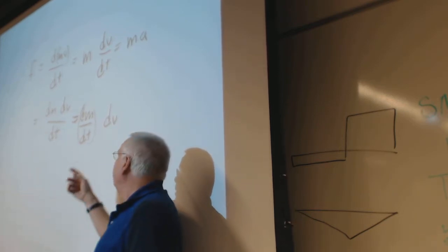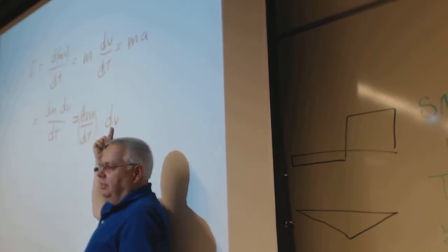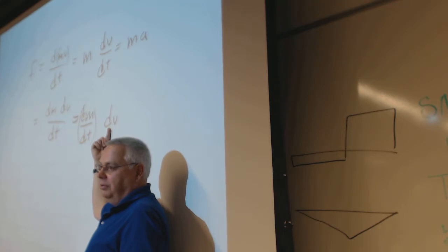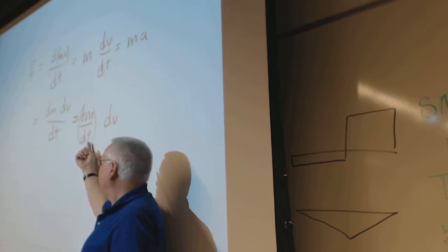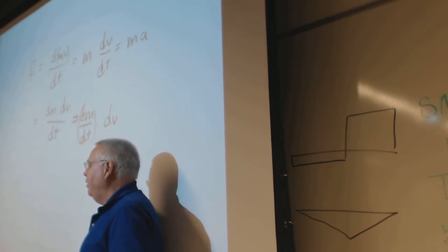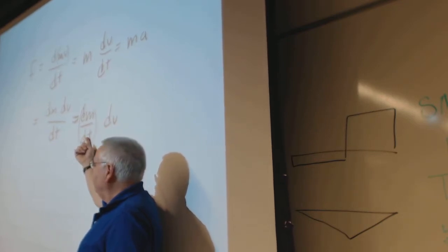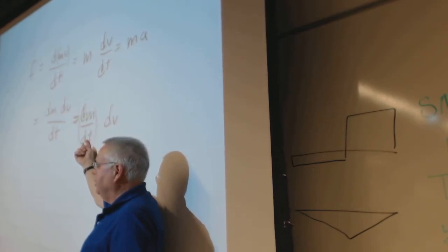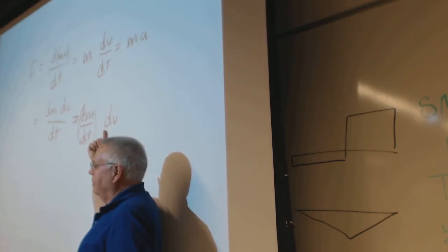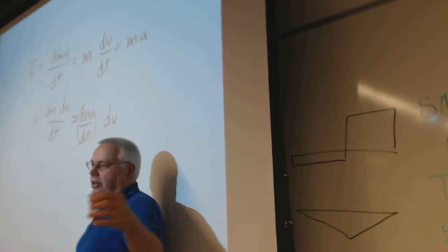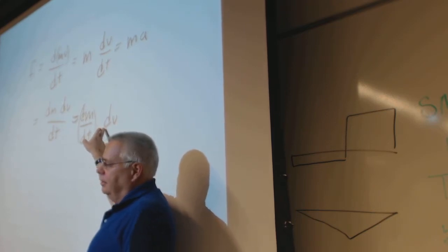You have a fan in the front flowing a bunch of air, a big mass flow rate, at the expense of the velocity. So you can't go supersonic with an engine from a 737, but you can be more efficient and quieter. If you need to go supersonic, you need this. Instead of using the power to blow a bunch more air past the engine, you live with it and use your velocity to get the change of air coming in, and then it comes shooting out the back faster. It's noisy and it'll go faster.